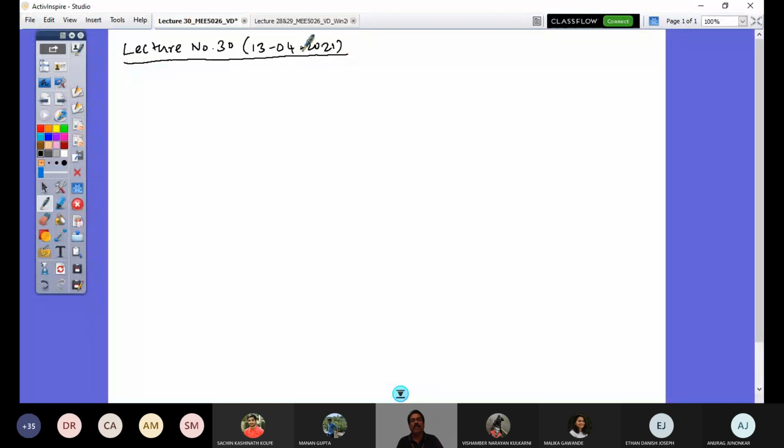We were doing it with the steady state gains, which are attained by the vehicle when you give an input, that is steering input. The steady state gains are what the vehicle feels as t tends to infinity, or as the vehicle is entering into the steady state motion, right? So those are called steady state gains, and those steady state gains are obtained from the transfer function, as we have seen. Transfer function is an important parameter as far as control system design of your vehicle is concerned.